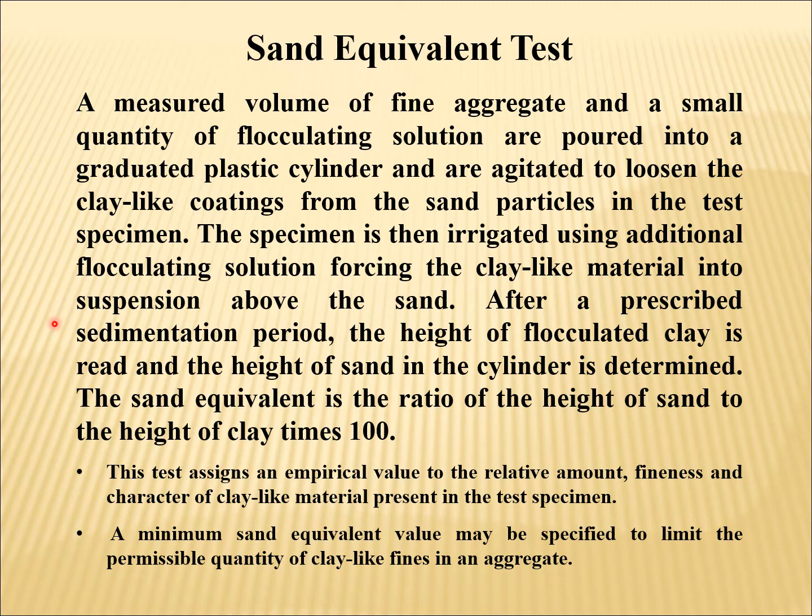After a prescribed sedimentation period, the height of the flocculated clay is read and the height of the sand in the cylinder is determined. The sand equivalent is the ratio of the height of the sand to the height of the clay times 100. So I will repeat that: the sand equivalent is the ratio of the height of sand to the height of clay times 100. So there are two important points which are mentioned.